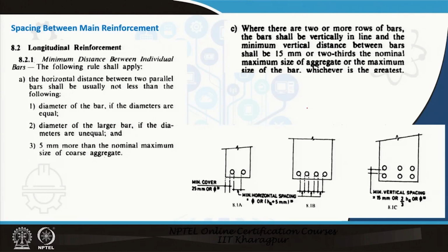See, suppose you have designed 5 such bars in the tensile zone of the beam. Those 5 bars are the design output, and how will they be arranged? Will they be arranged in such a way that there is no gap, or will they be overlapping each other? No, there are some rules, and those rules have to be taken from this particular detailing code.